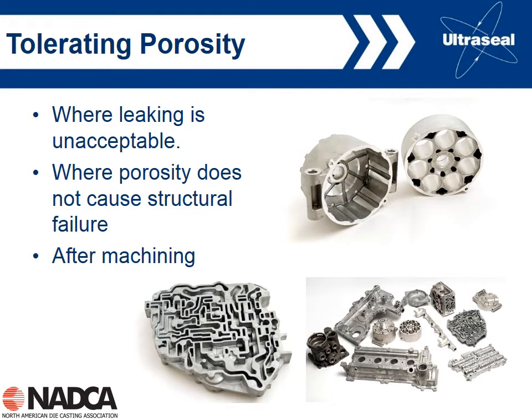So let's talk a little bit about impregnation while we talk about properties. We introduced impregnation a few slides ago, and basically, when should I consider impregnation? Well, obviously, you should consider impregnation when the leaking causes an unacceptable condition in the castings. So the type of casting shown here, valve bodies, valve covers. These are castings where all I'm concerned about is whether or not they leak. Don't really care too much about mechanical properties. They're not really a structural casting.